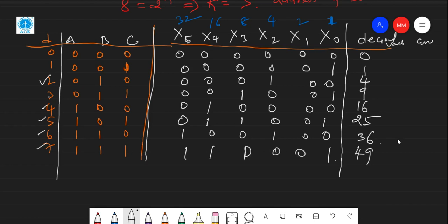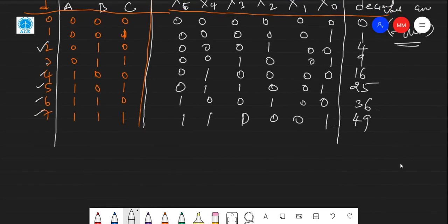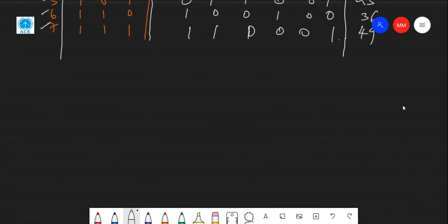Okay, now the function which I want is square. Square output I require. I want to program the square output at the OR level. Okay, OR logic, right? Anyway, AND logic will be fixed in the ROM, PROM. Now let us draw the design. So anyway, this is a 3 into 8 decoder. It's nothing but AND logic and decoder, this one, right?